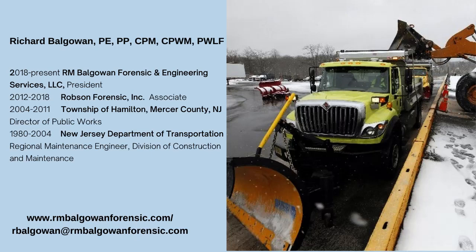Yeah. The other thing too, and I go back to some of the things Deborah was talking about, is there are pluses and minuses to everything. There are things that you can do to further reduce application rates for salting, but they do still have some negative effects. She talked a little bit about agricultural byproducts, beet juice. There's corn products out there that, if used, can result in a lower application rate. Most of those agricultural byproducts are natural corrosion inhibitors, and they allow salt to stay on the roadway longer, especially if you're putting it down as a brine. So they can reduce the amount of salt, but they also have negative impacts, like BOD and those types of things. So the whole key, I really think, is education.